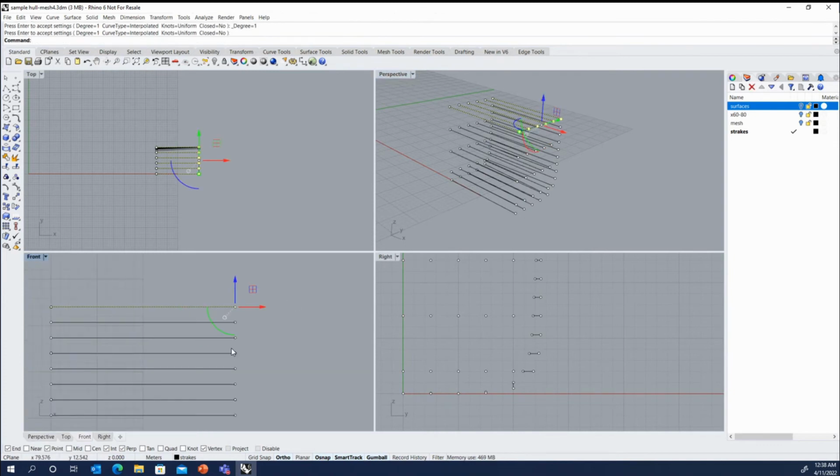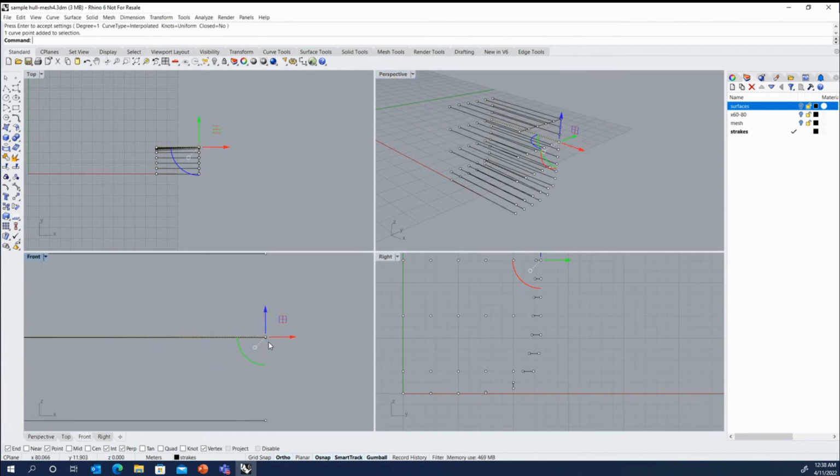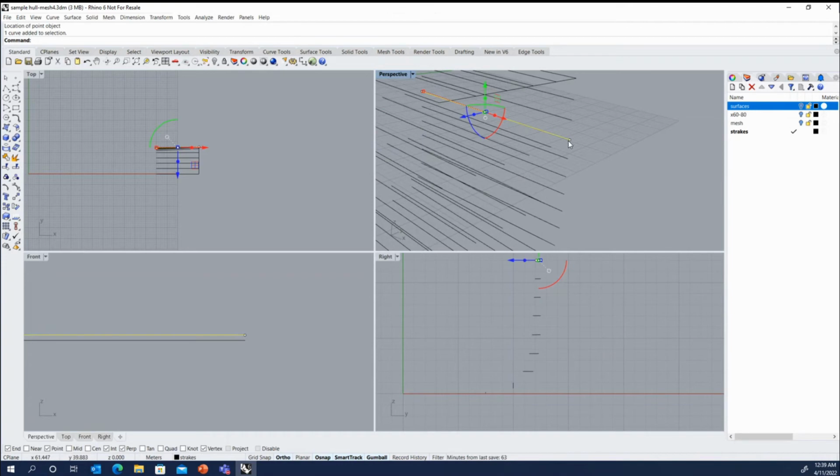And for the next one down, I know it's the third point below, but if I wasn't sure or had a much denser collection of points here, I could highlight one in this view, so it'd be identified in this view. And actually, when I zoom in, I don't know why those are slightly off. I'll have to look at that. Let's take a quick measurement here. That one is at y equals 12. That is at 12.01. So I think when I dragged that point back in and it snapped to an end, it must have been the end of a line segment that was very close to that deck end, but not exact.